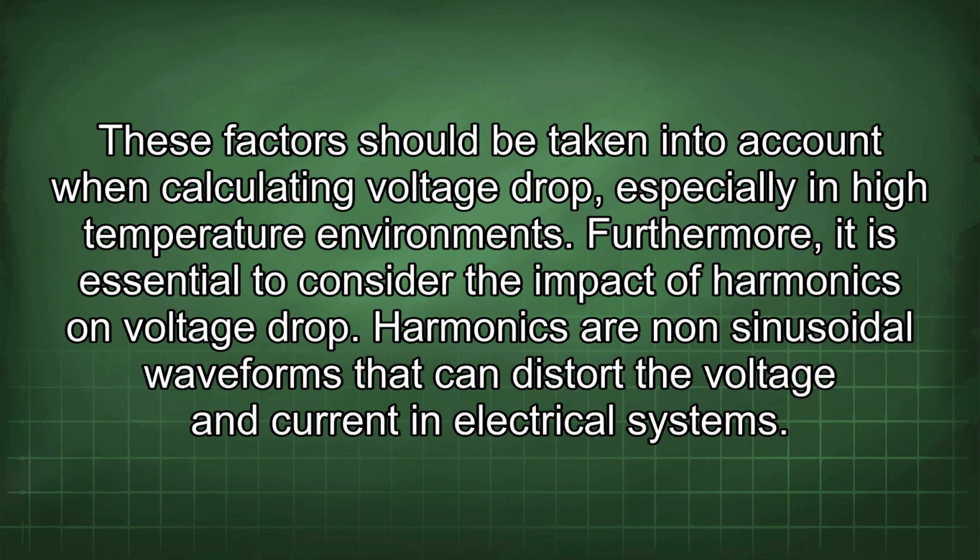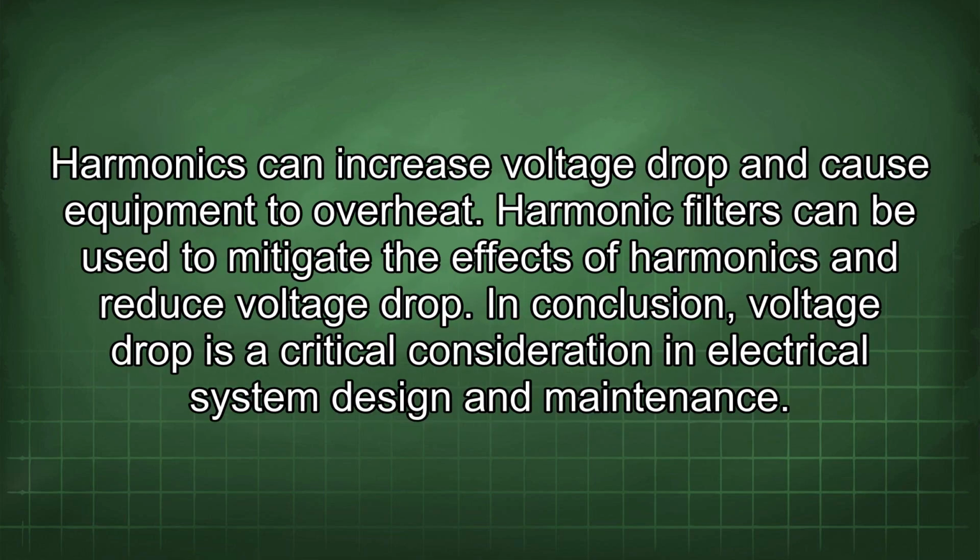Furthermore, it is essential to consider the impact of harmonics on voltage drop. Harmonics are non-sinusoidal waveforms that can distort the voltage and current in electrical systems. Harmonics can increase voltage drop and cause equipment to overheat. Harmonic filters can be used to mitigate the effects of harmonics and reduce voltage drop.